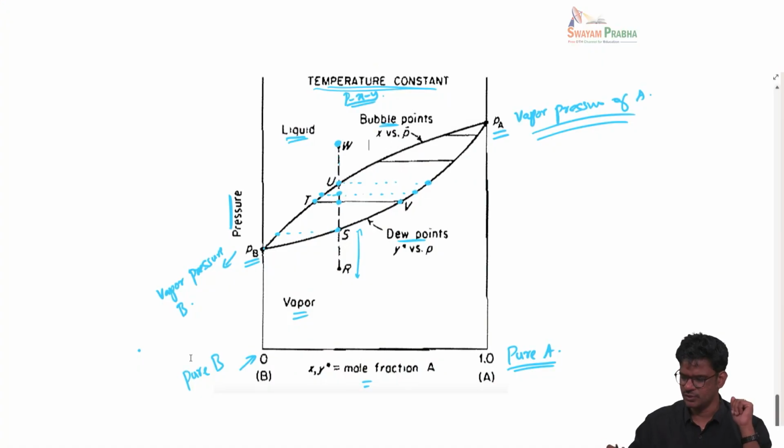Usually the students get confused between the bubble point and dew point when you go from TXY diagram to PXY diagram. Okay, the easiest thing to remember here is, intuitively you can expect whether at high temperature liquid is stable or vapor is stable. Similarly, in terms of pressure, liquid is stable or vapor is stable. So if you know this concept, you can identify easily whether the bubble point will be above or below for a given diagram. So like I said before, in this case also you can plot XY diagram.